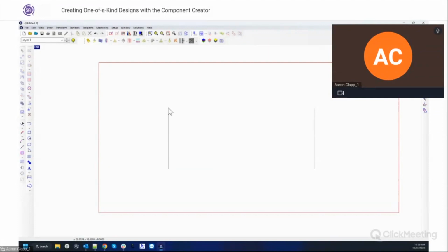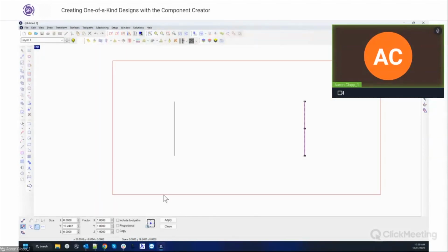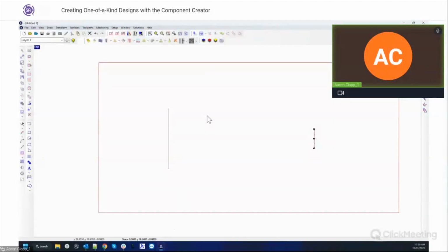And I'm going to create a cone shape. I want it to come down to not quite a point, but to sort of a flat edge down here. So I'm going to take this and make it smaller. We're going to go to scale, and scale in 2 dimensions. That's fine. I want to keep it in the middle. I don't want it to shift up or down, so I'm going to say position in the middle. And what do you think would be good? Maybe we'll do 6 inches here. Apply. Okay, so now we've got a cone-ish style shape.